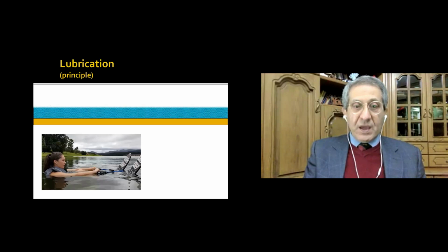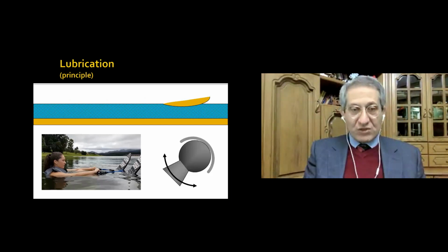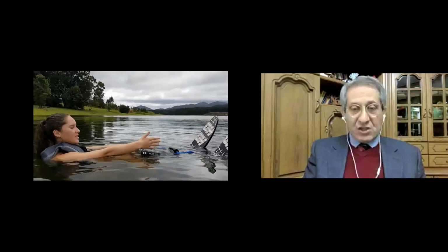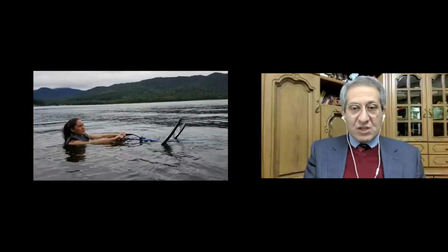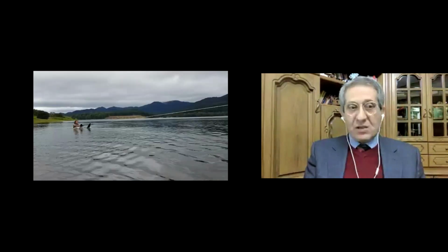Interacting surfaces need to slide relative to each other at a reasonable speed in order to maintain an adequate fluid film. This is much like water skiing. When the skis are initially stationary, the skier tends to sink in the water under her weight. However, once the boat starts to pick up speed, she is kept floating by the velocity of the boat and the viscosity of the water.